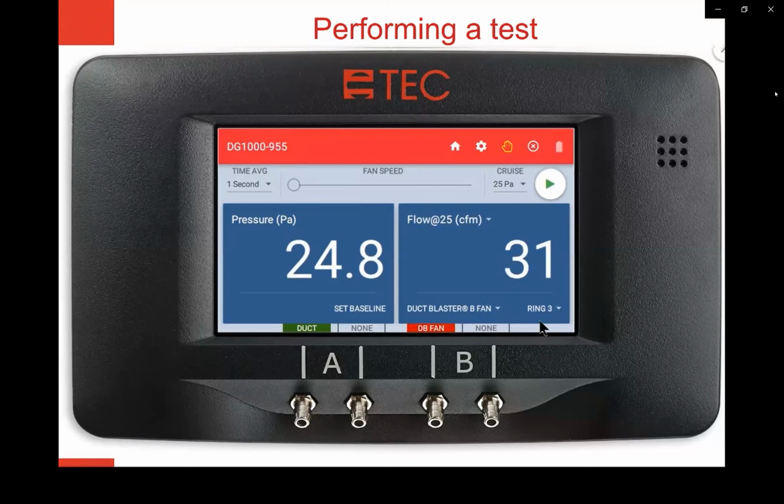So now we'll either turn up the knob or we'll click the cruise button, and that'll bring us up. We want to get within a couple of pascals of 25. We're in the pressure flow at 25 mode, so it's going to correct whatever that pressure was for 25 and display our results here. You can also click on the hold button, and when you push hold, it'll lock the screen and turn the fan off. So that's also convenient to have that option.